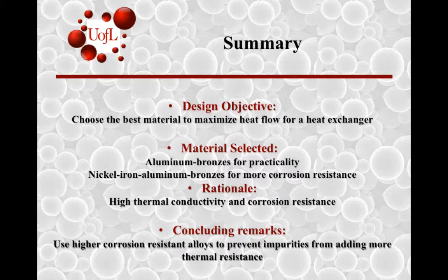And then concluding remarks would be that the case also mentioned that when you're using water, or in this case seawater, there are organisms in there that like to bond to the copper, which will increase thermal resistivity. So if you choose one with more corrosion resistance, those organisms don't really like those kinds of alloys. So I think it might be better to just go with the more expensive option.